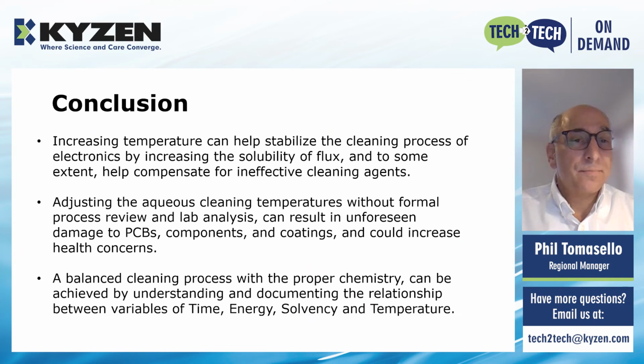In conclusion, when we're talking about the impact of temperature on electronics, increasing temperature certainly can help stabilize that process of cleaning electronics by increasing the solubility of flux. And to some extent, that'll help compensate for some ineffective cleaning agents you might be using.